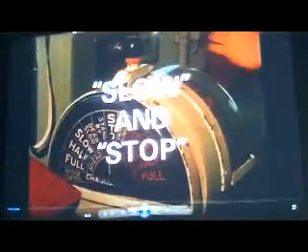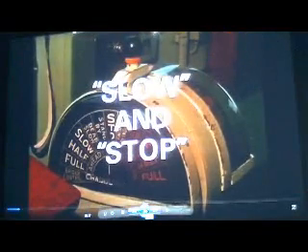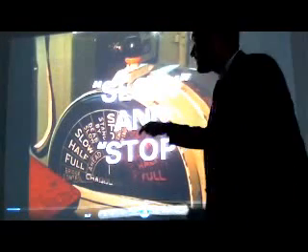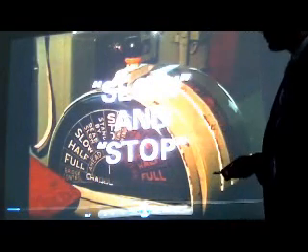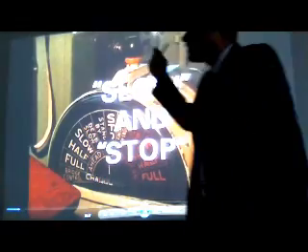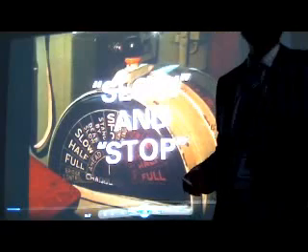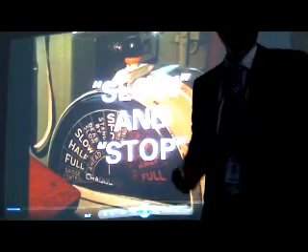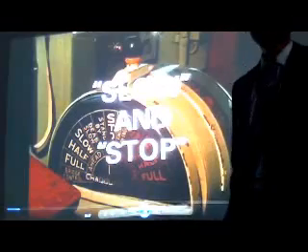Did you just see this? This is this vessel's telegraph. In our simulator, it is not going to be like this, so I'm highlighting it to you. It is one of the controllable factors that we were talking about: propulsion. You cannot increase your vessel's RPM by 1 RPM, 2 RPM, 3 RPM. The vessel engine is designed, generally a slow speed diesel engine, to work at certain levels of RPM.